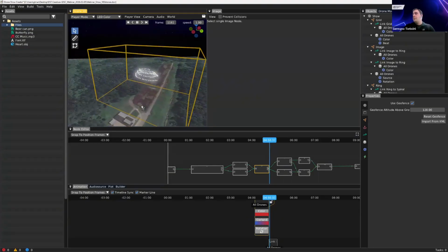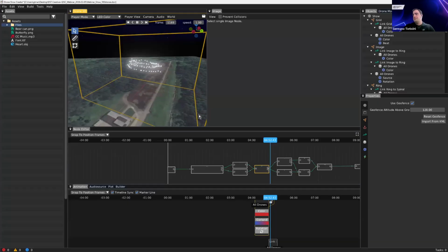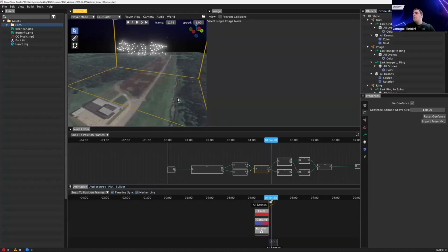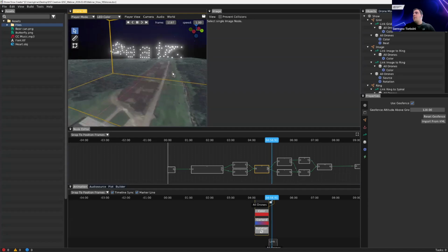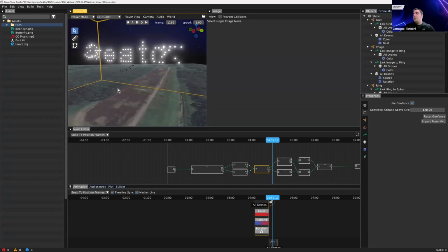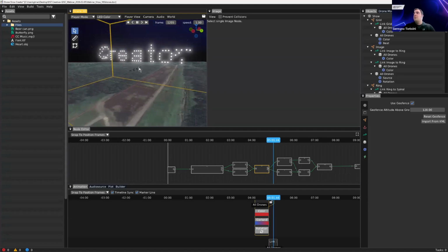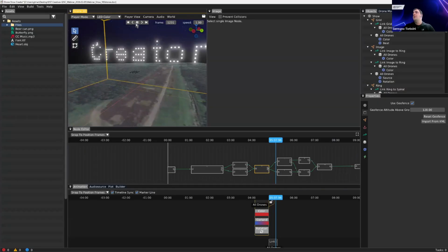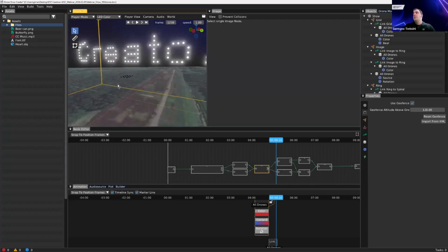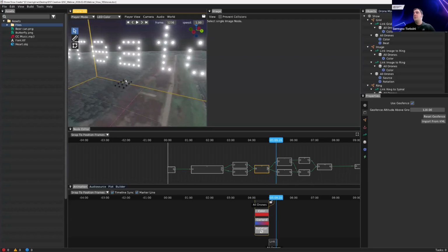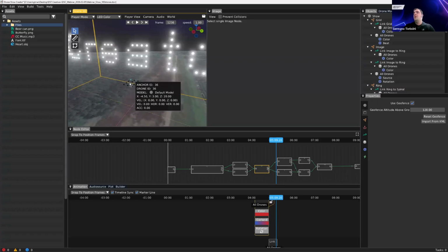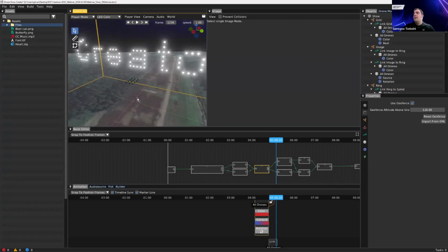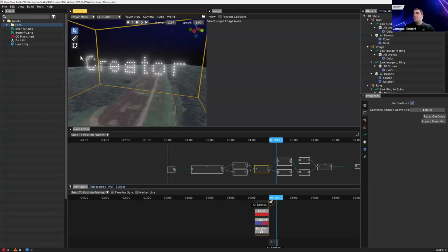And there is our next figure. Our next figure is text. And here is another thing you'll be doing quite a lot in designing drone shows. Sometimes you cannot or do not need all the drones for your figure, and you need some drones to just hang around in reserve, right? If we look closely, I have some 12 drones in reserve. They have their LEDs turned off. No one will notice them in the night sky. They're just waiting around for the rest of the drones to run their figure.